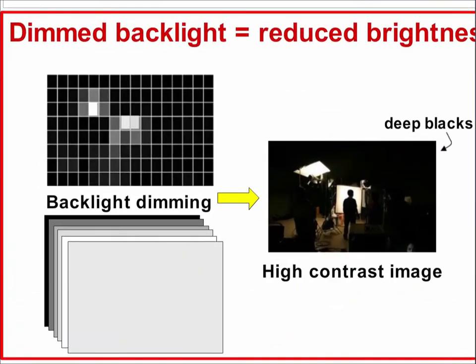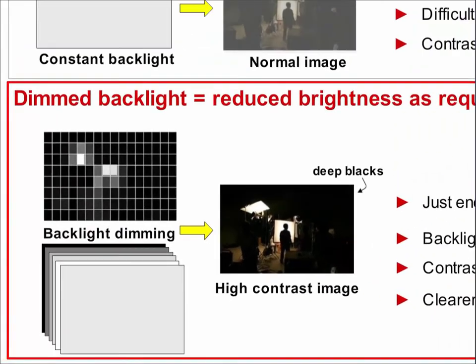In the lower example, we see how the various LED blocks of the backlight unit are modulated to produce light as desired for the picture. In the white areas, the LEDs may reach their highest brightness. The darker areas require only a little backlight, so the LEDs in these areas are dimmed or even off. As a result, the contrast of the image has increased a lot.